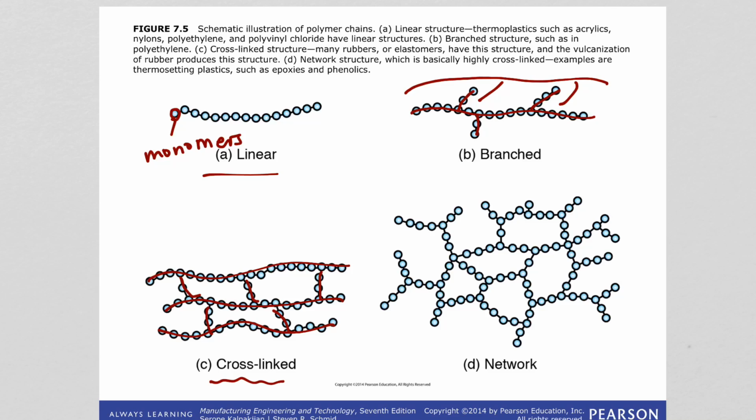Cross-linking has a major influence on the properties. It increases hardness, strength, stiffness, and, of course, brittleness. It provides better dimensional stability. So in our car tires, the rubber is vulcanized. It's called vulcanization. That is actually the forming of these cross-links in between the chains. So this way we achieve strength.